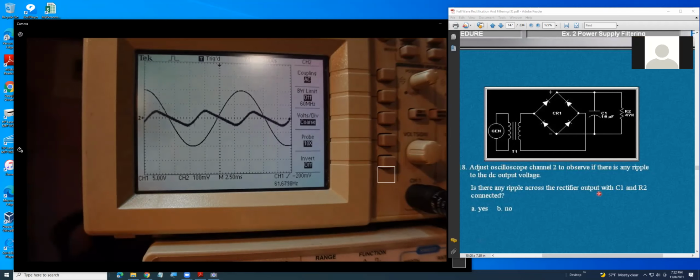Is that ripple adding stability to the frequency? What's the primary purpose of the ripple? You have to design it by understanding that the capacitor charging and discharging depend on the time constant. We already know tau equals R times C. You want the time for charging to be much longer than the time for discharging.